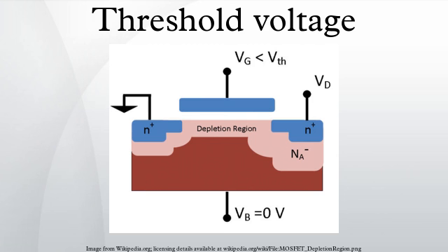Looking above, the threshold voltage does not have a direct relationship but is not independent of the effects. On average this variation is between -4 millivolts per kelvin and -2 millivolts per kelvin depending on doping level. For a change of 30 °C this results in significant variation from the 500 millivolt design parameter commonly used for the 90 nm technology node.